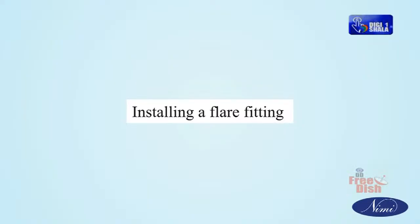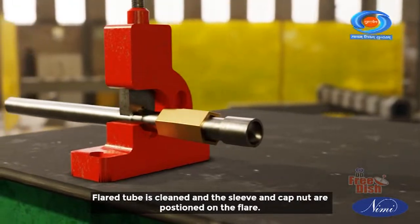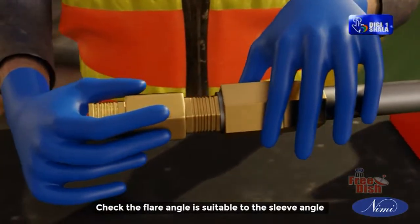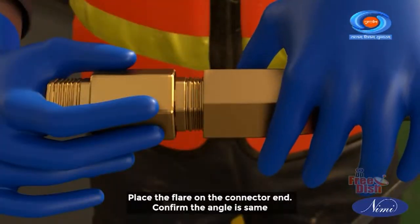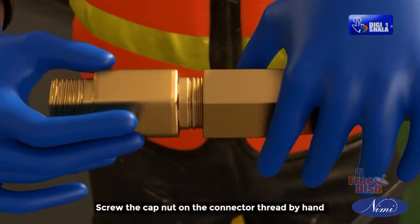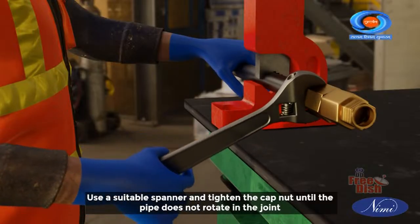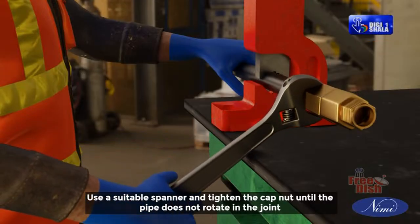Installing a flare fitting. The flare tube is cleaned and the sleeve and cap nut are positioned on the flare. Check that the flare angle is suitable to the sleeve angle. Place the flare on the connector end. Confirm the angle is the same. Screw the cap nut on the connector thread by hand. Use a suitable spanner and tighten the cap nut until the pipe does not rotate in the joint.